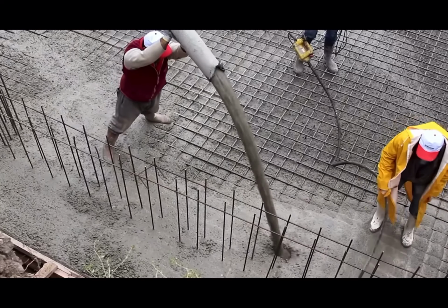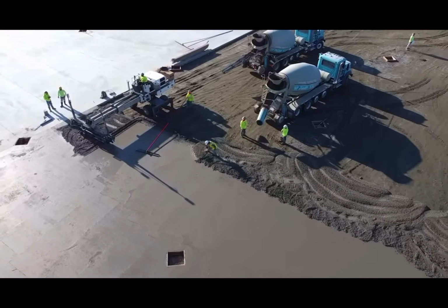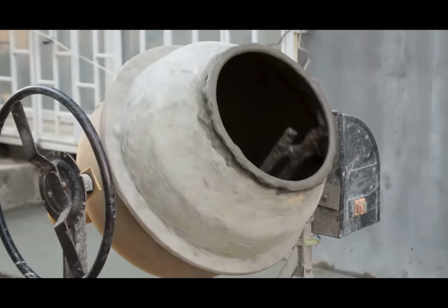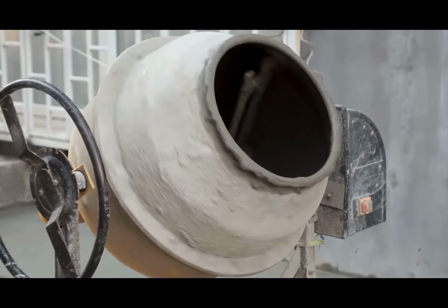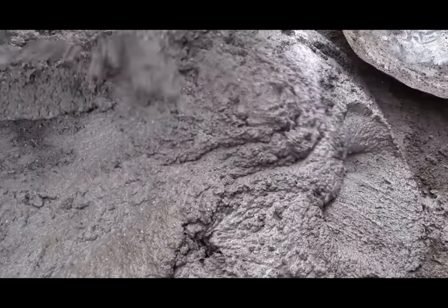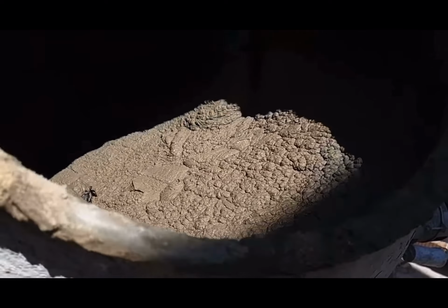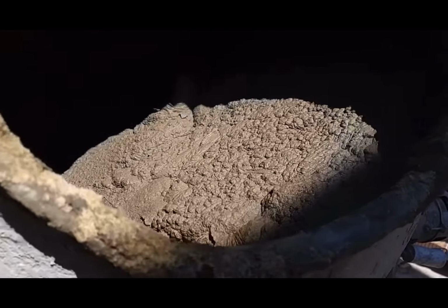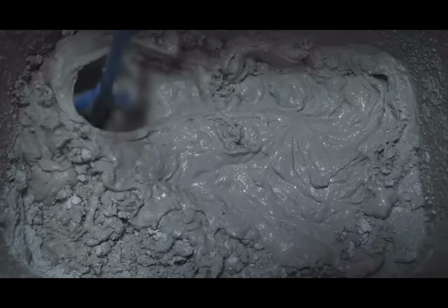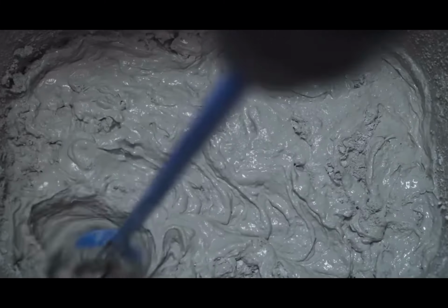Moreover, building codes have been developed that specify the ratio of cement, aggregate, and water based on the different types of construction. The next step is to mix the ingredients thoroughly to create a uniform mixture. Traditionally, this was done manually using shovels on a flat surface such as a concrete slab. However, nowadays, concrete mixers are commonly used, which automate and speed up the process. The mixing process ensures that the cement particles are evenly distributed throughout the aggregates.